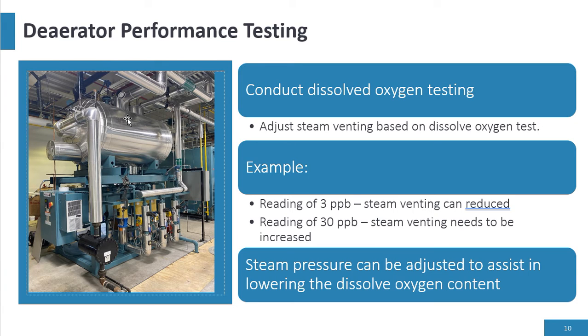We always say a deaerator should operate at 6 psi. That's just a ballpark number. It can be 9 psi, can operate at 5 psi, 15 psi, even today if a deaerator is operating at 100 psi. It's just to make sure that the deaerator is getting rid of the non-condensable gases.